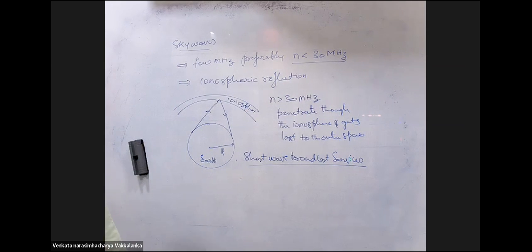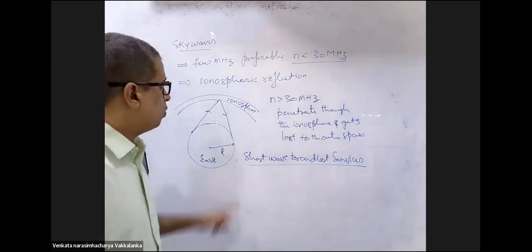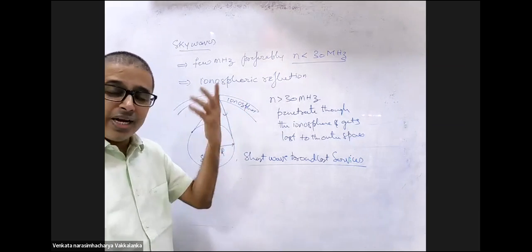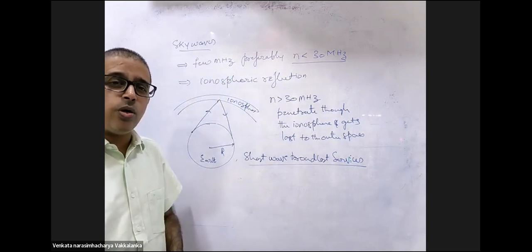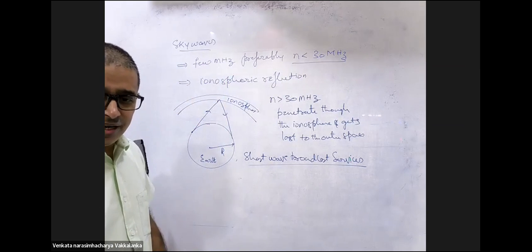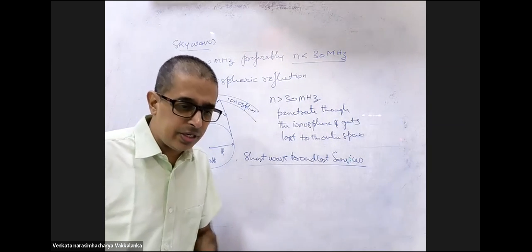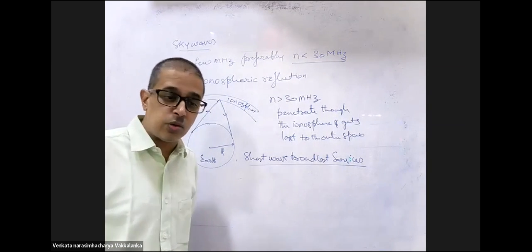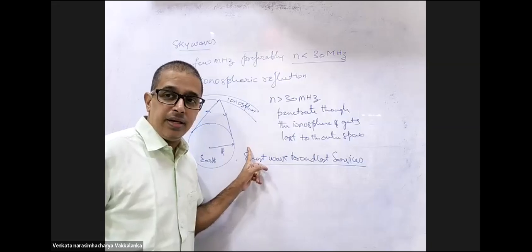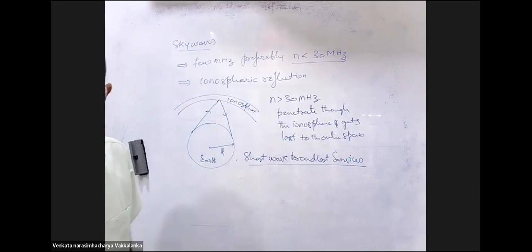Sir, the frequency should have a lower bound to it as well, right? Because the layers below the ionosphere, it should penetrate them. That dies due to attenuation. Frequency lesser than 10 megahertz will die due to attenuation. But you can transmit it through skywaves. They will be reflected, but the signal strength goes down. Not that you cannot transmit it. Okay, sir.